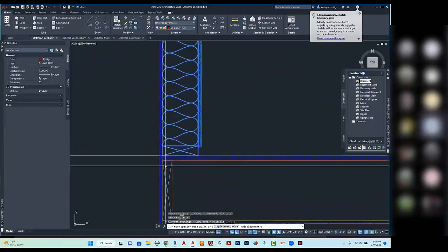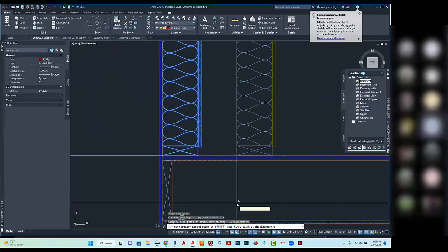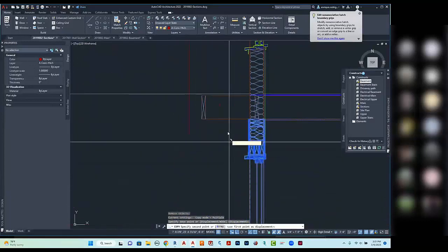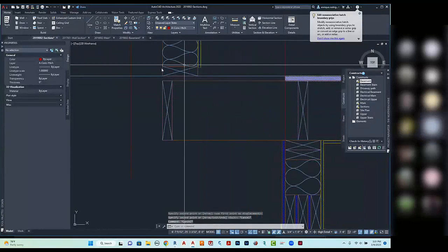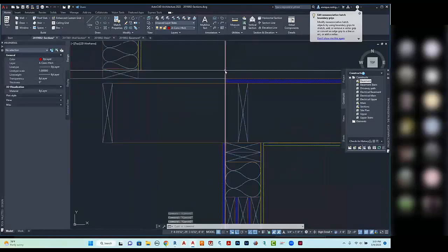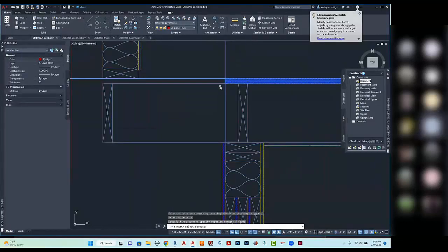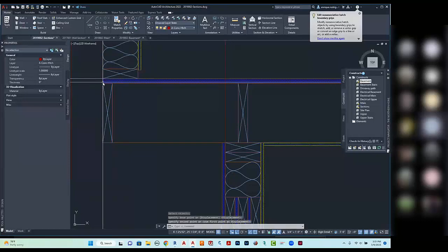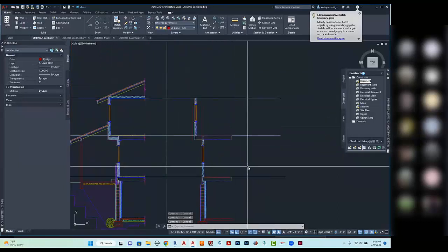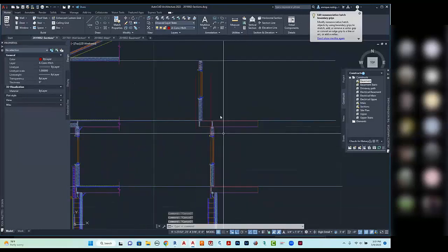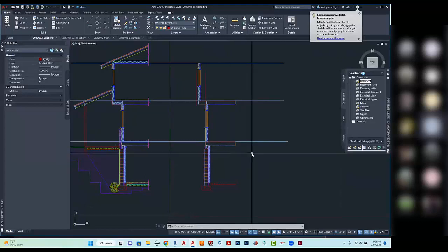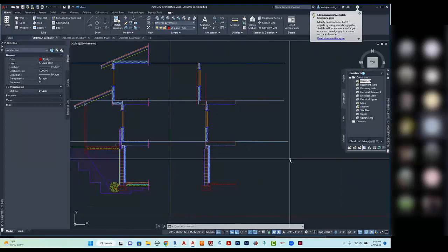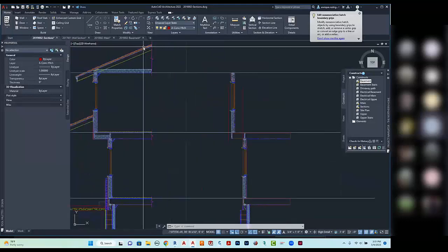Okay, I'm going to copy it from top of the ribbon joist here to the top of the ribbon joist here, and then I'm going to go ahead and take my plywood and stretch it out, line up back here. Using the stretch command, grab it back here and pull it over to that point right there. Notice how quickly, once you have enough of these elements drawn, that you can reuse and get this section working a lot faster. So, all right, so let's see what's going on at the top of the roof here.